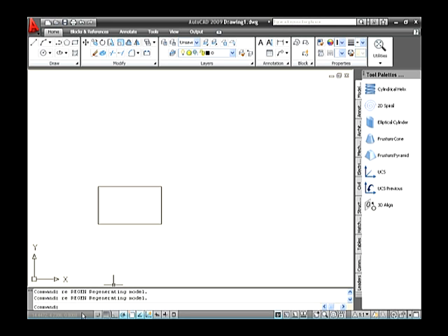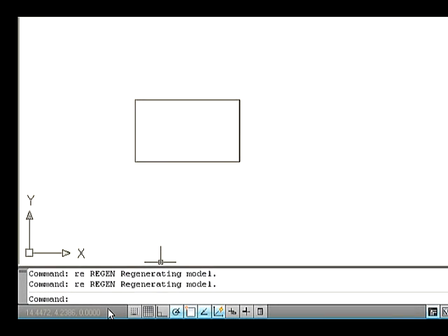Coordinates of the crosshairs. It is similar to the previous version in AutoCAD, whereas the style and look is more appreciated. The coordinates readout displays the current X, Y, and Z location of the crosshairs on the drawing area with respect to the origin point. If the coordinates in the lower left corner of the screen are grayed out, coordinate tracking is turned off. Click the coordinates so that they appear in dark numbers, which change when you move the crosshairs in the drawing area.